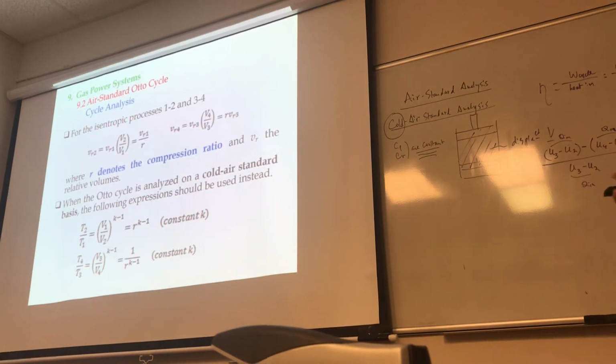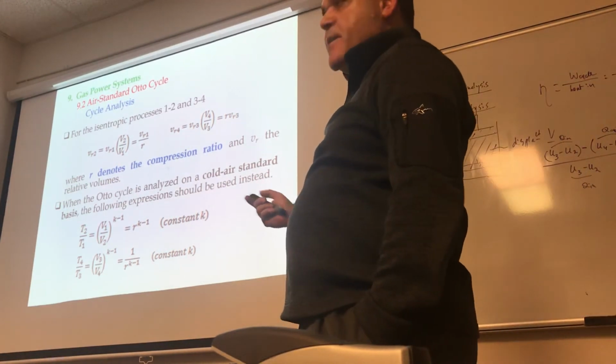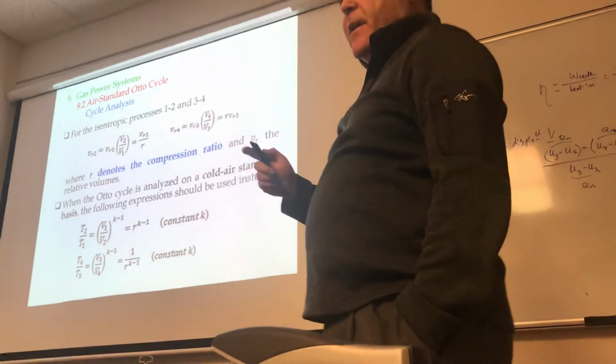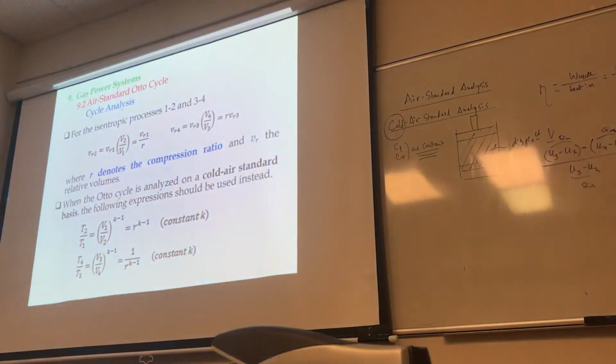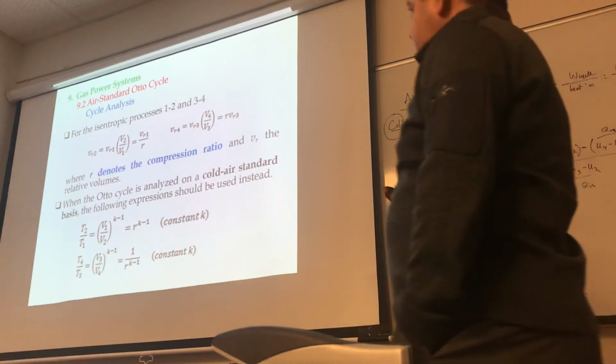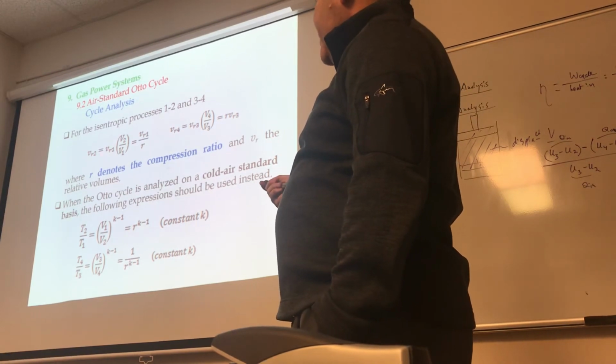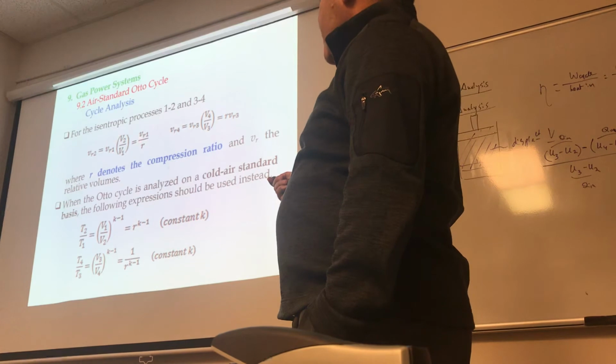Now, still in the cycle analysis, for air we will be talking about 2 isentropic processes, right? And we talked about this last term, towards the end, I think, of chapter 6, if I recall, because that's where we were talking about entropy and isentropic processes, and we were using the vr values, right? We will be looking at an example. So we use what we call the relative volumes and the relative pressures. In this case, the relative volumes, as you go from one state to the other.